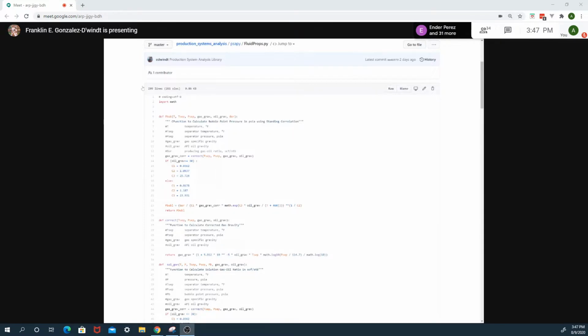All right, and we also have another very nice library, which is for the multi-phase flow. We have two. We have Beggs and Brill. We know very well about this correlation. And we also have Hagedorn and Brown. We have tested more Beggs and Brill than Hagedorn and Brown. I've made some tests. It's working fine, but I can't guarantee it's bulletproof right now.